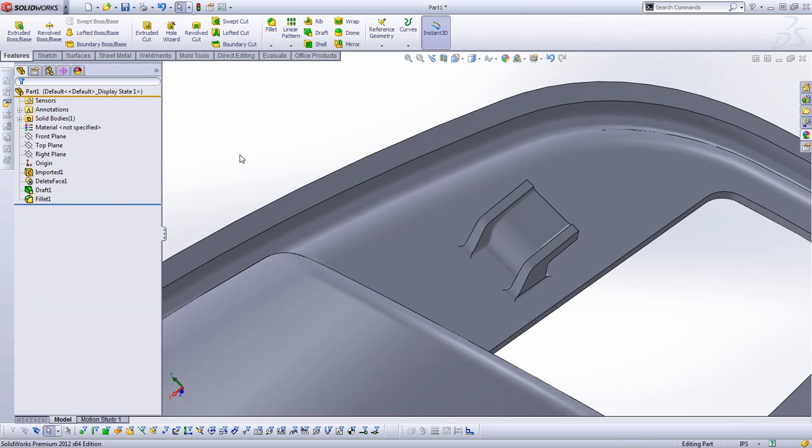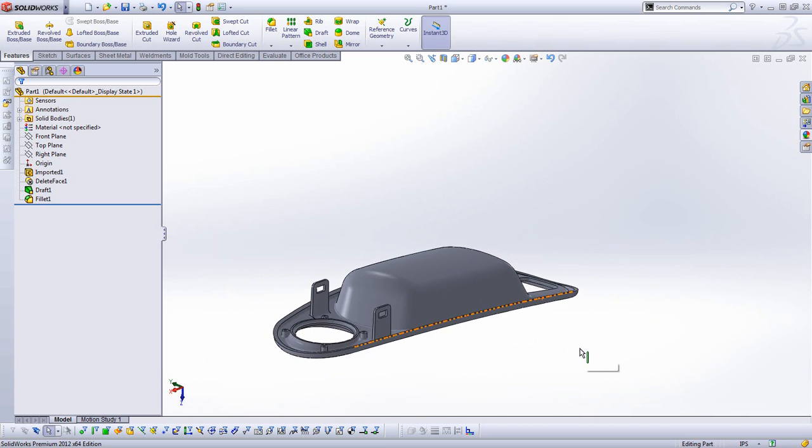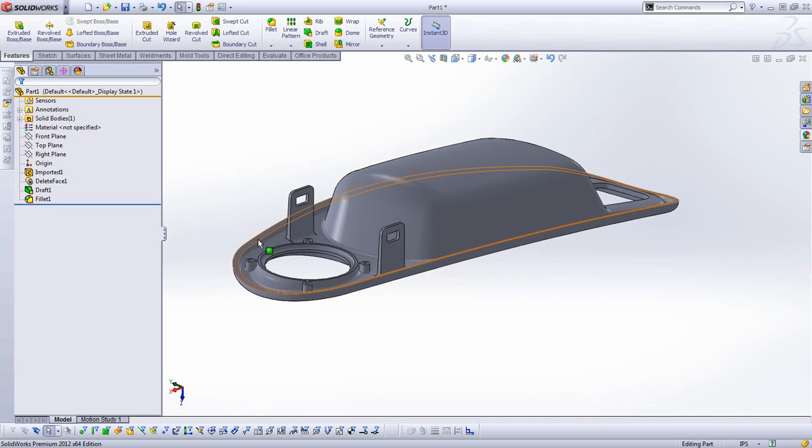So if I look at this part, I would really want to take a look at my parting line. If I rotate this around, you can see that this face would probably be the best candidate because it's a clean split. We probably wouldn't want to have a seam on any other part of the model. It cosmetically would be a good area for it. Every job is going to have its own particular areas that lend themselves to a parting line. But if you can have one persistent face rather than having it jog all around, it's going to be a lot easier to machine, a lot easier to handle as far as SOLIDWORKS goes. So we'll go and take a look at the parting line.